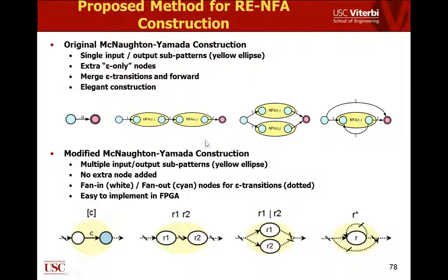So we came up with an alternate construction here. We call this the modified construction, the lower portion you see here. The key idea here is that when you combine these regular expressions, why not allow multiple transitions? Therefore, I can increase the out degree of a particular node at the expense of increasing the out degree of the nodes we have when we connect these individual expressions. I would like to make sure that the long wires are only wires of length equal to 1 in the connecting edges we have. Length equal to 1 meaning that I don't have to go from A to B, B to C, C to D kind of connections coming into the picture here. That means that every time I do an epsilon transition, I'm guaranteed that I have a non-epsilon or a character transition that is going to be effected.